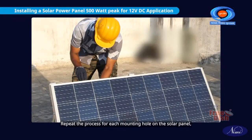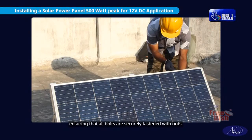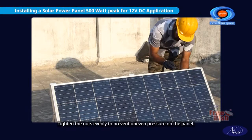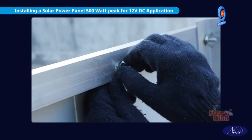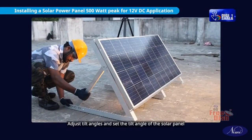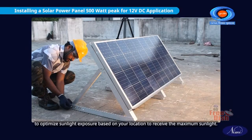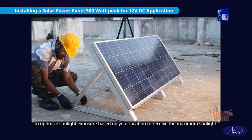Repeat the process for each mounting hole on the solar panel, ensuring that all bolts are securely fastened with nuts. Tighten the nuts evenly to prevent uneven pressure on the panel. Adjust tilt angles: set the tilt angle of the solar panel to optimize sunlight exposure based on your location to receive the maximum sunlight.